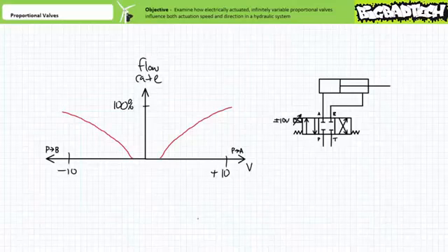because remember that flow rate through a restriction, like a regular flow control valve, or a fancy proportional valve, will be greater given a larger pressure differential across it. The cap end, having a larger functional area, would necessitate less pressure to extend a given load. This means a proportional valve will experience more of a pressure differential during extension at a given applied voltage and more flow as a result. It should be noted that there exist pressure-compensated proportional valves that provide a constant flow rate regardless of variations in pressure upstream or load-induced variations downstream.